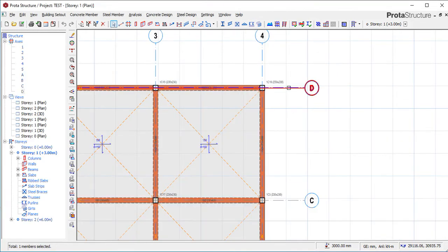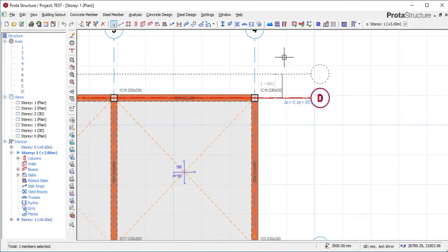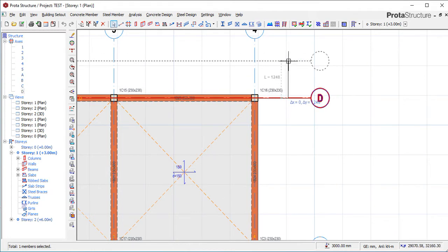To offset, you click on the grid line you want to offset, right click on it, and you will see Offset. Click on Offset. Please pay attention to what you do next, because with this you don't know the exact distance you want to offset to. If you miss this, you miss it all. Right click Offset, move to the side you want, then hold down the function key and click F2.